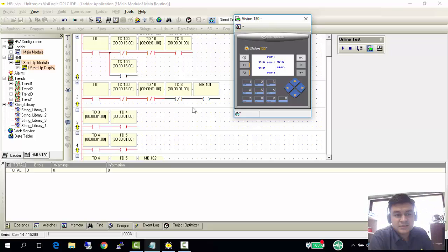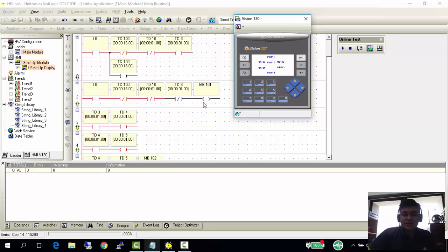4, 5, 6, and 7. So after 2 loops is over, you see that my DD100 is now open. Because of that open, the DD100 here is being cut off. So with this cut off, now you see blank. So that means no more looping. So you can also use the timer to replace the counter functions as well, so that you don't need to design for the counter reset. So timer can work alone.